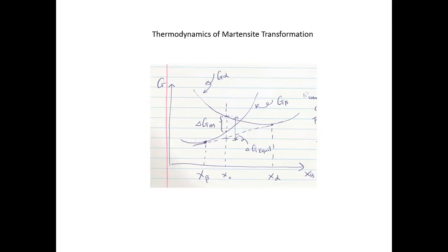Yes, I got a question. So basically, precipitation, nucleation and growth are both diffusion controlled, right? More precisely, the growth of the precipitate is diffusion controlled. The nucleation is also related to diffusion, but more like fluctuations. If you want to see a nucleus form, you still have to give the system enough thermal energy for the fluctuations to occur, right? But the subsequent growth will mainly be diffusion controlled. For quenching, because everything occurs very quickly,